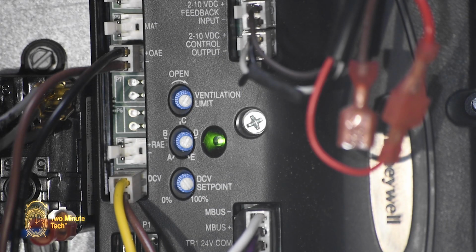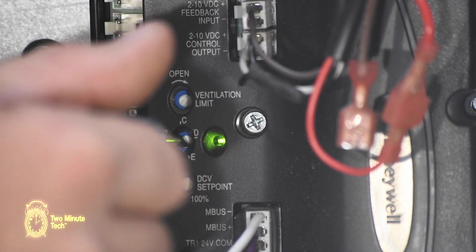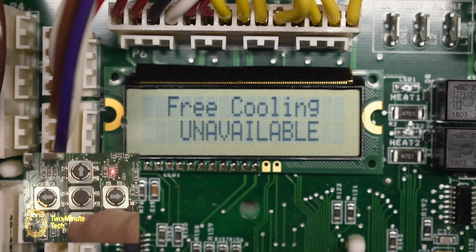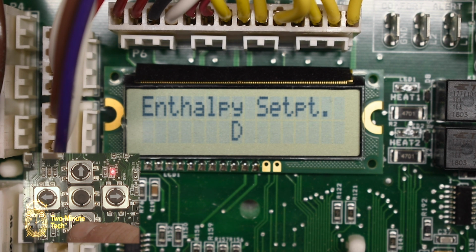Using a small screwdriver, rotate the potentiometer so that the arrow points to the required enthalpy zone letter. At the Clear Control, go to the economizer menu and use the down arrow to go to the enthalpy zone setting. It should read the new value.